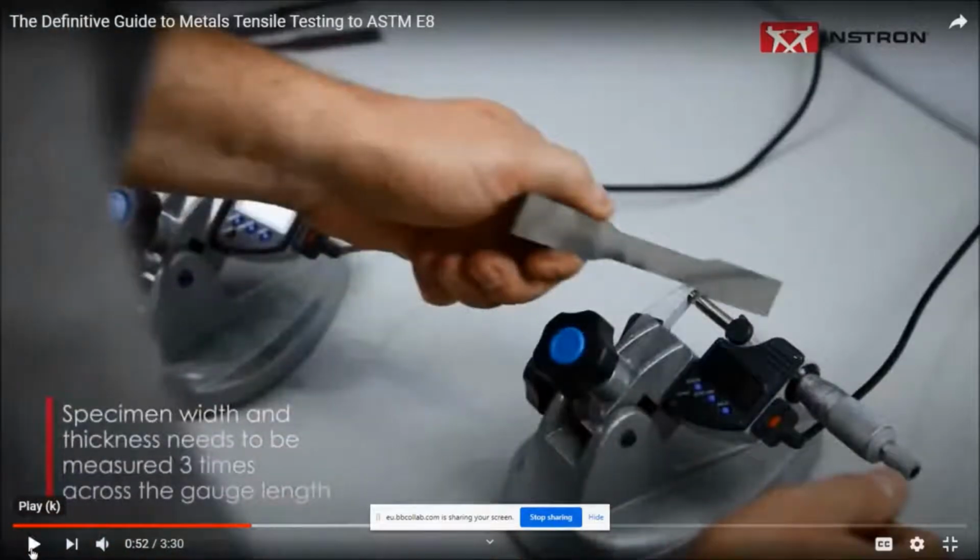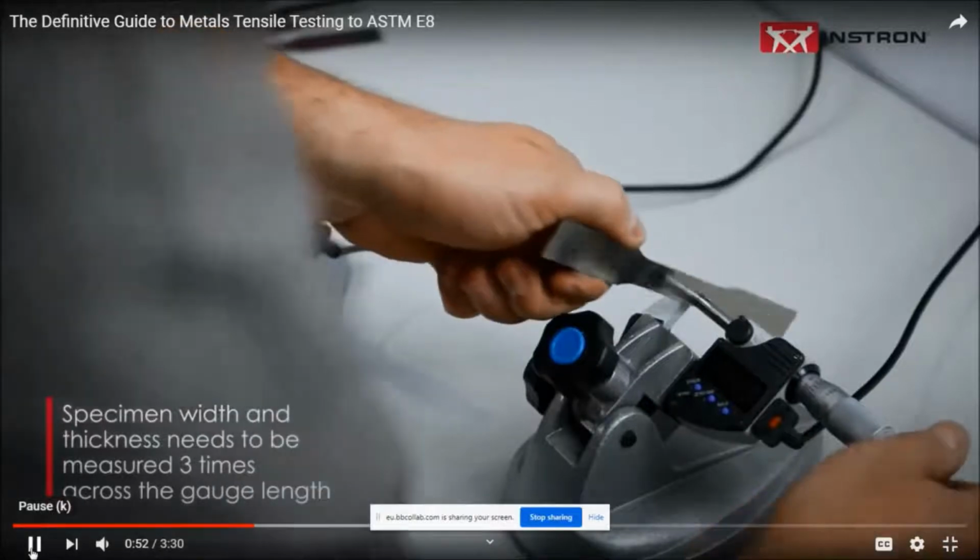It's important to remember that you always have to ensure that the test specimen is properly manufactured, is properly cut, and that you control the dimensions of this material. For that reason, we usually measure the thickness of the specimen at 3 different points at least, right? Because if you have a smaller or higher thickness, you will have different loads on the machine, or you will have different deformations on your specimen, right? In this case, they're using a micrometer to measure the thickness.